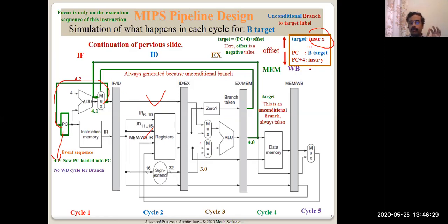Suppose there was a subtract instruction, R1, R2, R3, here, which came here and started decoding and started fetching the values. It has only read those register values, and maybe it would even have performed the operation, but by the time it came, we had actually loaded the new value.